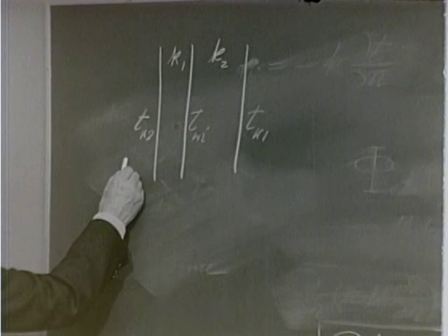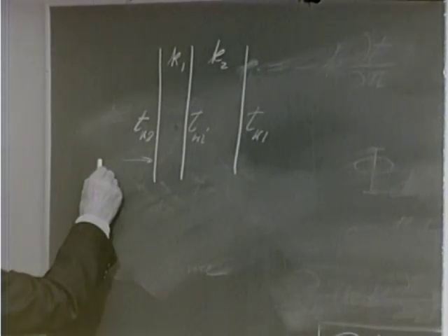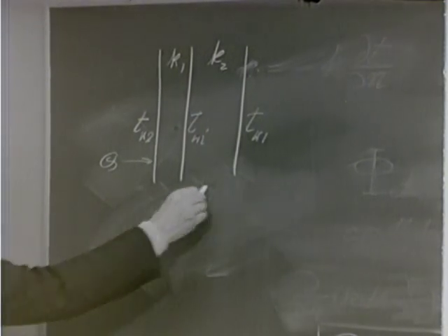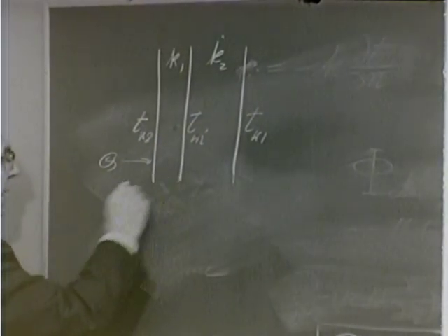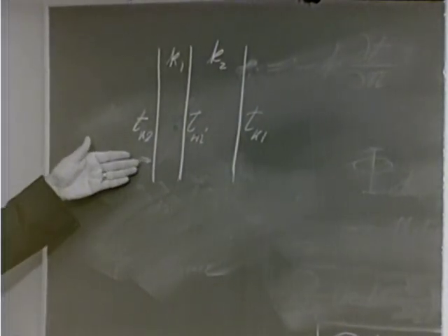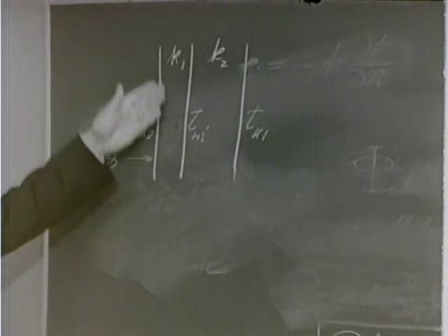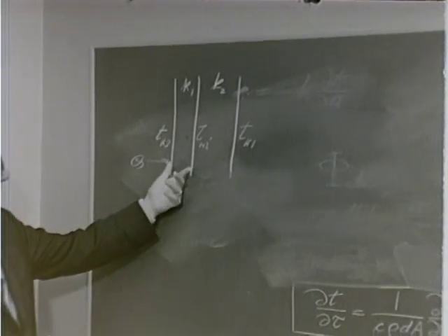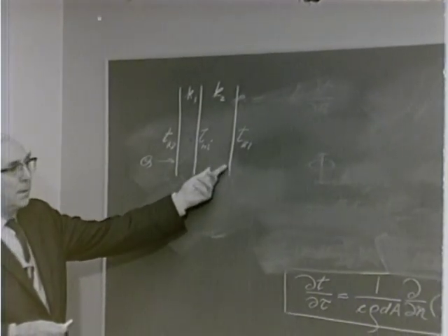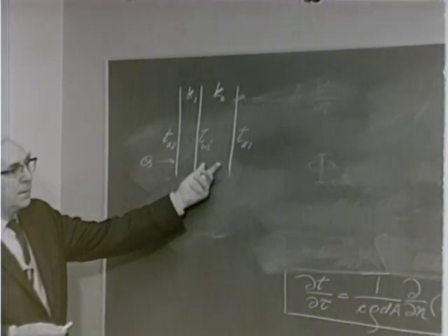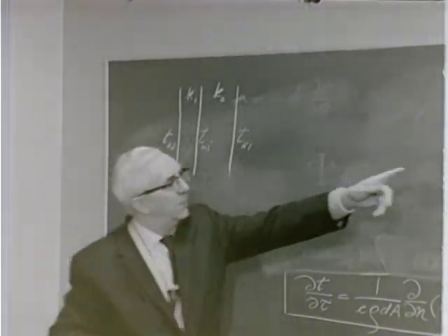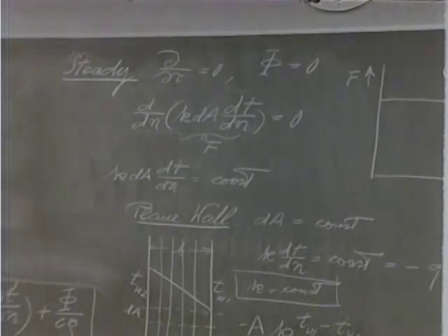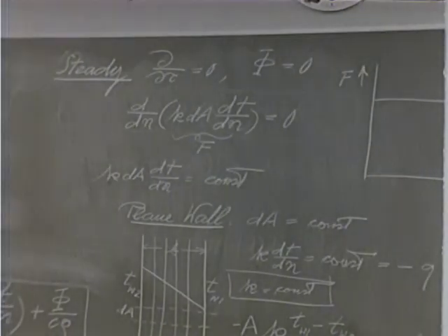Here we would again want to calculate the heat flux, Q. And in steady state, obviously, the heat flux has to be the same through any isothermal surface as I move along, because in steady state no heat is stored in the interior. And in addition, we have assumed that heat generation in the interior is zero.